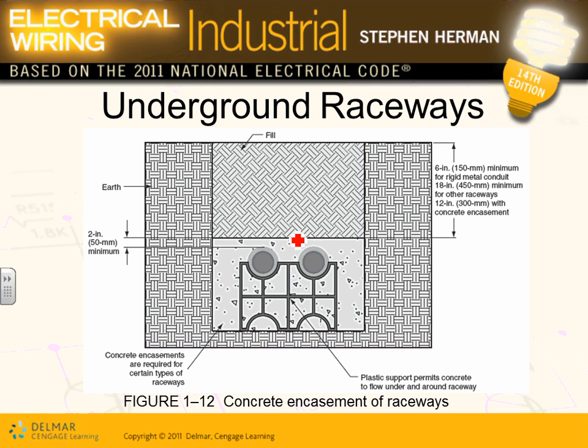When it comes to bigger systems, they don't direct bury them. They put them in ducts, encased in concrete. So here's how they do it, gentlemen and ladies. You have ducts over here, and inside these ducts is concrete. You can see the whole concrete here, and then they bury them from 6 inches all the way to 18 inches: minimum 6 inches for rigid metal conduit, 18 inches for other raceways, and 12 inches with concrete encased. If you have concrete encased, you have 12 inches.